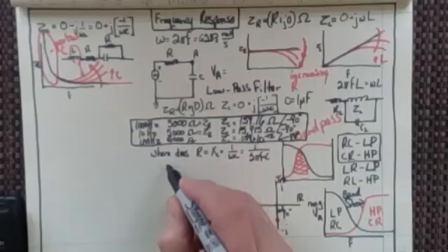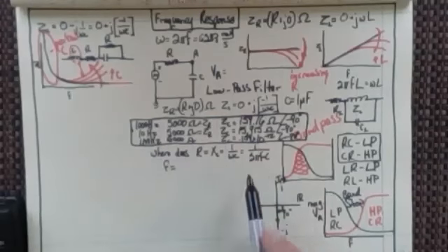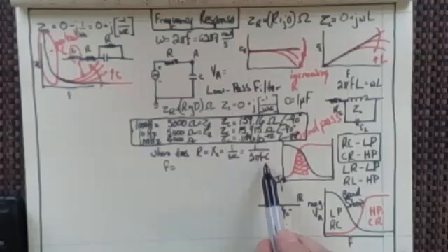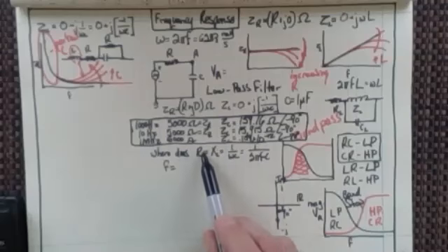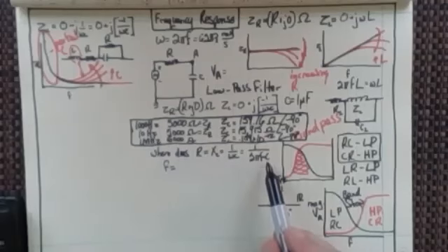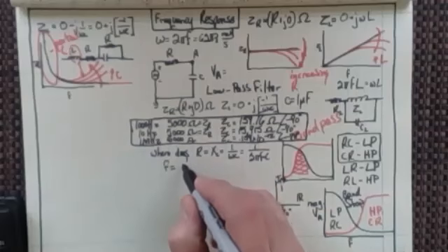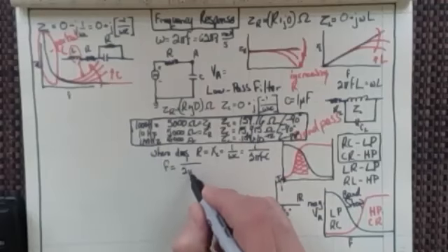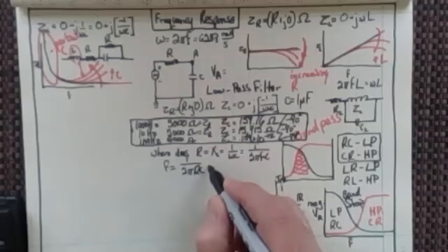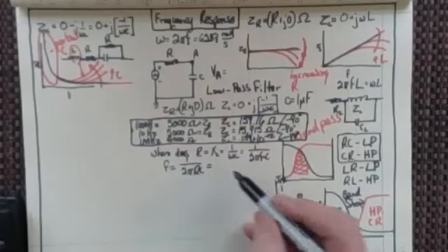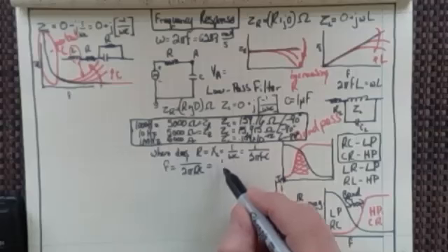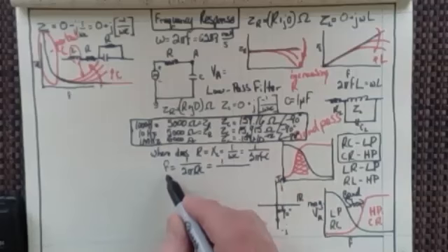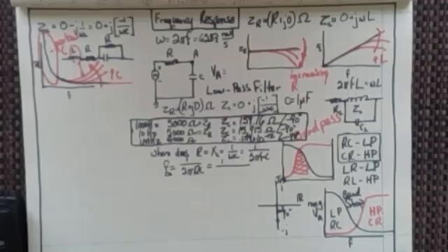At what frequency? Well, let's take the frequency out of the denominator on the right-hand side and put it in the numerator over here, and then take R and put that down in the denominator here. So that would just be 1 over 2 pi RC, right? And so let's find that. We actually call this the cutoff frequency.